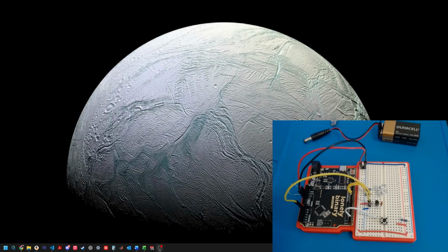For this lab, we are running on an Arduino Uno, and we are using a TMP36 temperature sensor to record temperatures over 5 minutes in a refrigerator and then 5 minutes at room temperature, outputting that data over serial and plotting it.